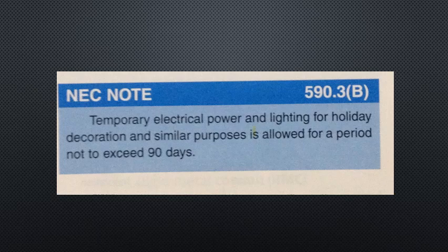Temporary wiring installations are allowed for the purpose of providing power and lighting to facilities during construction. Temporary wiring can also be used for testing, experimental, and developmental purposes. Upon completion of the activity, the temporary lighting must be removed. Bear in mind that Article 590 simply modifies the code requirements, and except for those specifically modified under that article, all other requirements of the code apply.